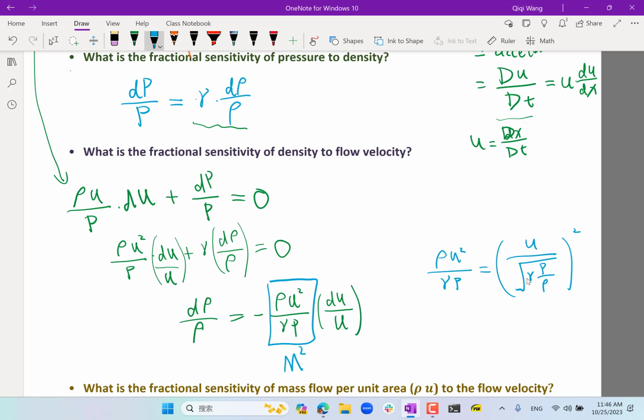So basically negligible, right? But as the Mach number rises, let's actually think about the squared Mach number, because the Mach number itself is more difficult to think about. If the squared Mach number becomes 0.5, it is already significant, right? Velocity increasing by 1% means the density decreasing by 0.5%.